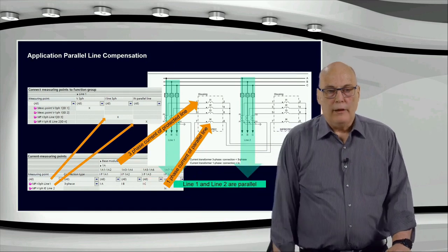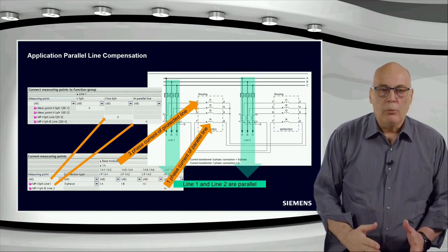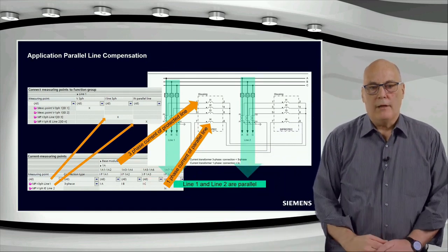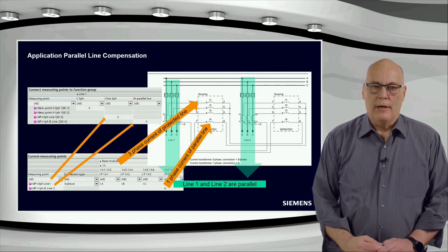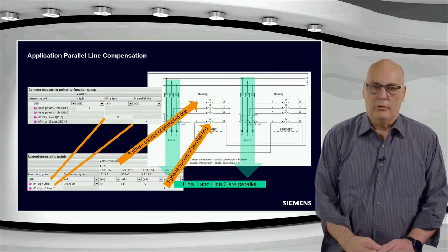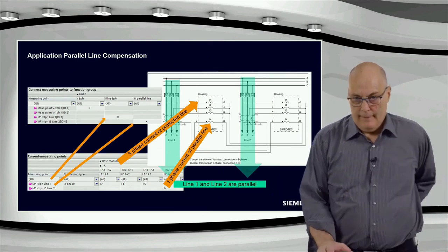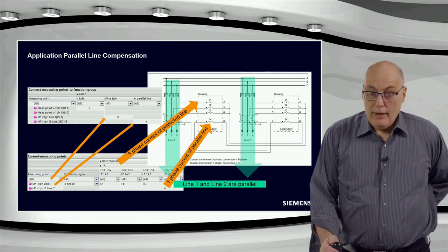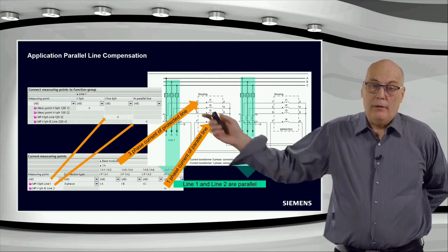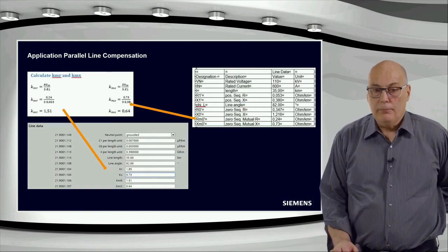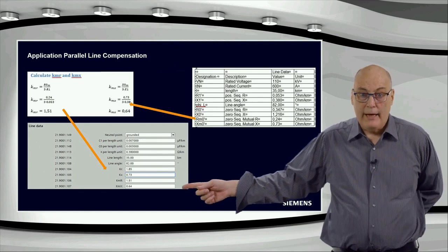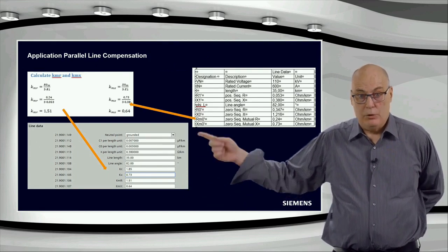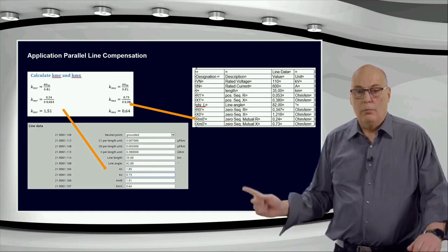You can see on the complete left, I renamed that current measuring point I, one phase, IE, line 2. So you know it's the line 2 IE current, for example. You can rename it as you desire. That's important. So if you've done that, if you have a parallel line current, then you have the option in the settings you see at the bottom here. You set that KMR and KMX, which we have calculated at the top.